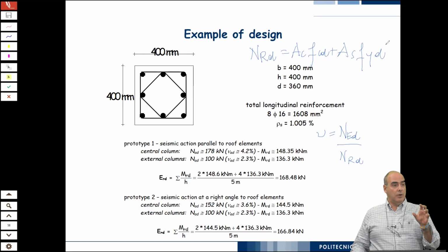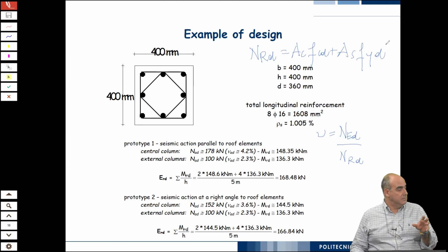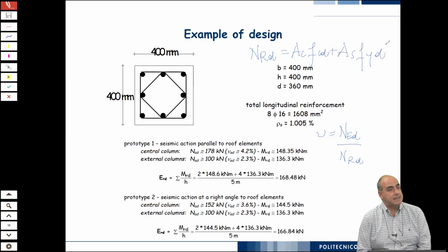You see that these columns in this precast mock-up were very lowly stressed, just a few percent of their capacity. Actually, this sometimes happens in precast building structures, because these elements have to be designed also, especially when it comes to earthquake, for maximum drift. And maximum drift is 1%. So we did the calculations, and actually with these sizes, we were exactly at the very limit.